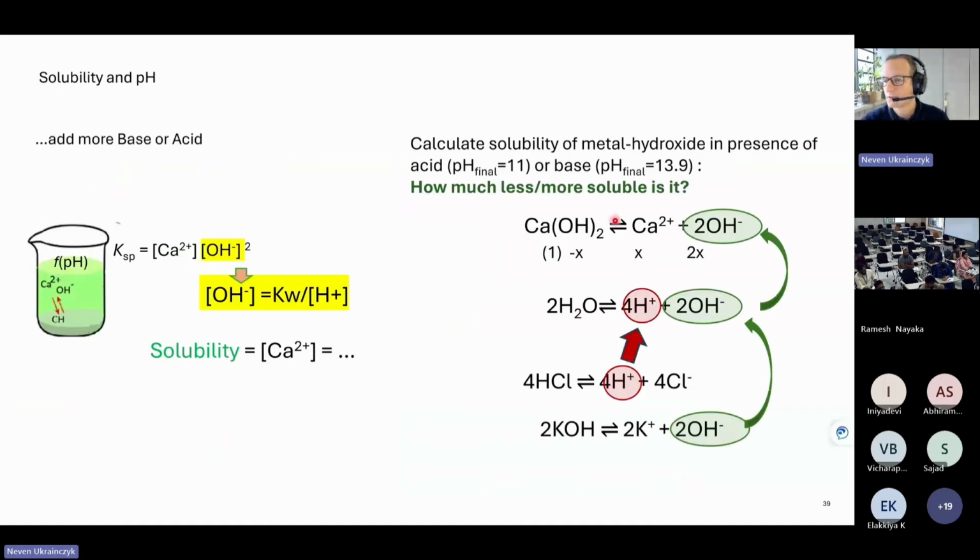But because we have also potassium ions in the Portland cement, which are dissolving from cement clinker, this potassium is always hydrolyzing water, and you have the OH minus. So how many potassium? You always have so many OH minus if you have a pure system. But now we have a mixed system actually. We have a portlandite and KOH, and this OH minus actually is now adding here. So this will shift the equilibrium. It will precipitate more portlandite.